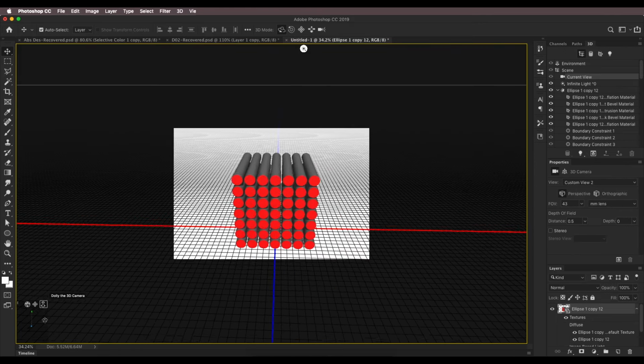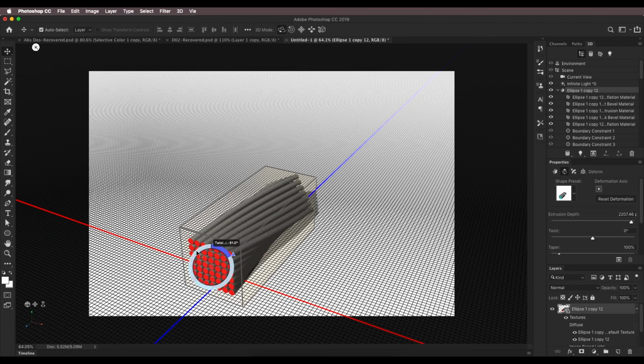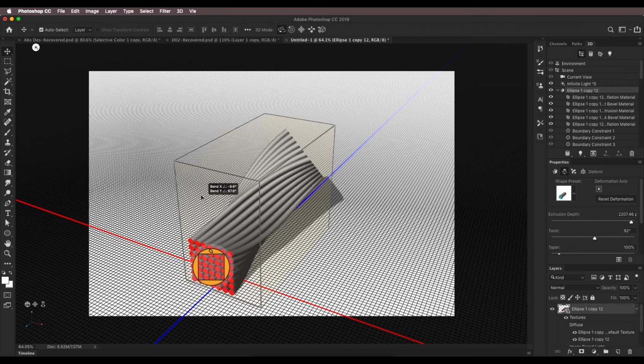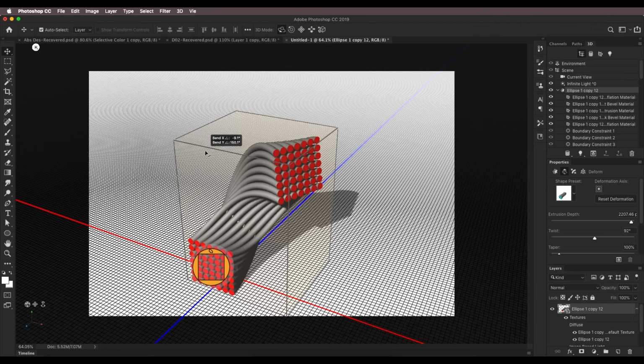If you checked out our previous tutorial, you already know what all these attributes mean. So I'm going to extrude it a little bit like this, around, let's say 1500. Now click outside and go to the perspective view like this, and now let's apply taper. So selecting the deform option, and here just click and drag, and you can twist it. So we'll twist it in a way, and then we'll also give some curve effect. So like this, you can give some curve look like that.